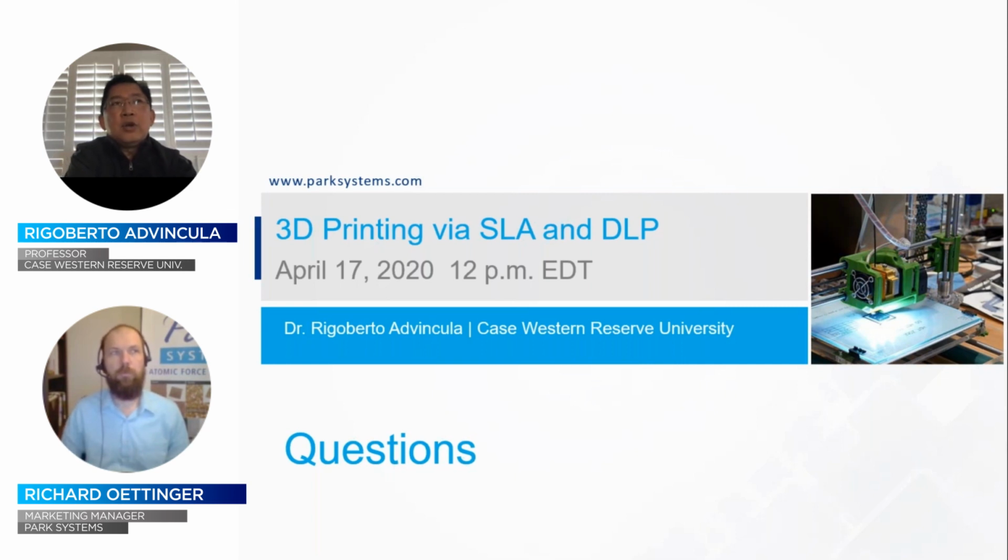However, nanofillers are known to aggregate. And if they aggregate, they can produce lumps even up to micron sizes, or non-separated nanofillers. So what I would advise is, as a nanofiller, it's best to use them at concentrations below 1%. If you end up using them at 5%, and especially if you don't see any improvement in properties, then most likely the nanofillers are just aggregating. So I will always like to try 1% and below to have the right percolation threshold and performance cost effectiveness, because after all, these nanofillers are more expensive than the traditional filler materials.